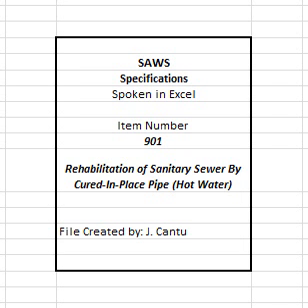The quantity of resin used for tube impregnation shall be sufficient to fill the volume of air voids in the tube, with additional allowances for polymerization, shrinkage, and the loss of resin through cracks and irregularities in the original pipe wall. A vacuum impregnation process shall be used. To ensure thorough resin saturation throughout the length of the felt tube, the point of vacuum shall be no further than 25 feet from the point of initial resin introduction.